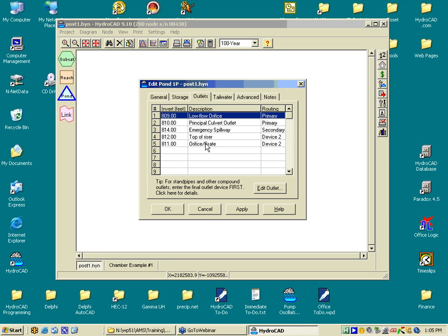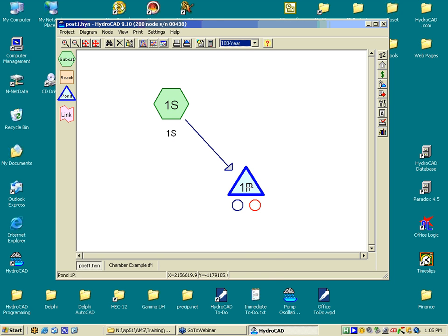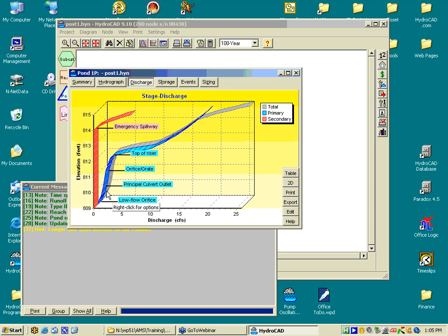So going back to the side orifice we had, if that was just, let's say, a 1-inch hole, we could specify the number of openings we have, and this can include columns. If it's perforated up, we'd specify that there are 8 rows, and we could put a 2-inch spacing between the rows. So that's the way you'd handle a perforated pipe, and just click OK, and we're all done. We now have those perforations right up the side of the riser.